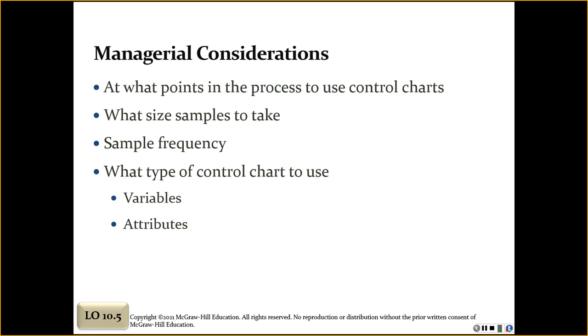Sample size is very important for two reasons. The first reason is because cost and time are functions of the sample. So the bigger the sample size, the bigger the cost of inspecting that sample is going to be. The other reason is that smaller sample sizes are more likely to reveal some type of change in a process than a larger sample size would, because a change is more likely to take place within a large sample than between small samples.